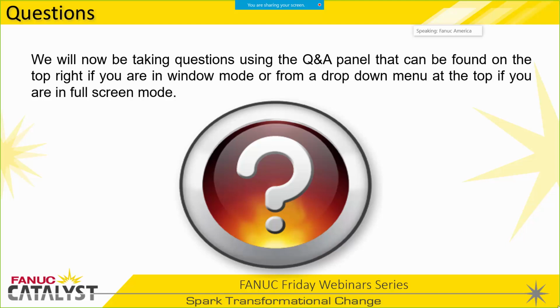Another question here: what is a typical cycle time in iRVision? Well, that's a hard question to answer, because obviously it depends on what you're looking at. The fastest I'll say with R30iB, the snap time is just the raw image transfer time. For a high resolution image, which we call high resolution 1280 by 1024, it was somewhere in the neighborhood of, I think, 140, 150 milliseconds. That's just to get the image in.